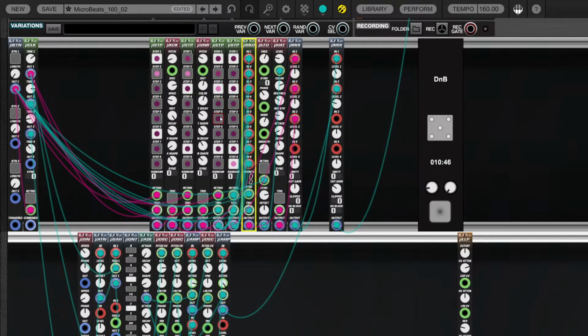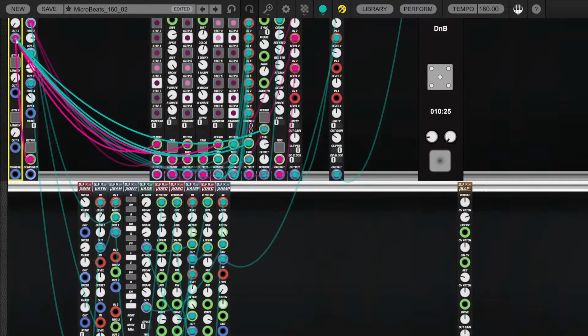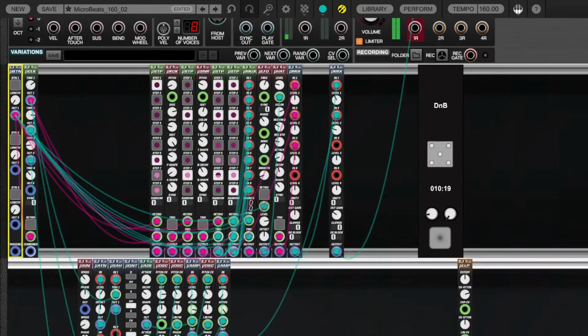Now these two sequences are out of sync, so we need to sync them once, and then they will stay in sync. You do that by re-triggering them via this input, and the easiest way is to use a button. I oftentimes wire a button output to all of the re-trigger inputs of everything that I need to re-trigger. Typically sequencers like the step sequencer, the CV sequencer, the clock.